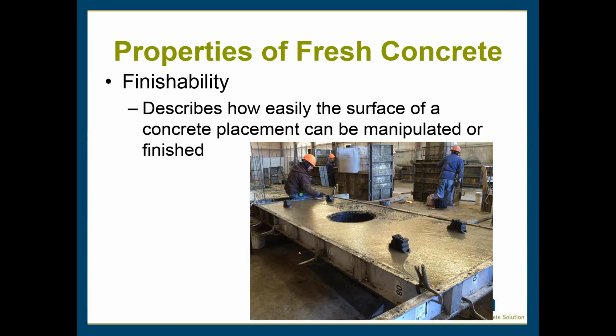It makes it a lot weaker, and sometimes if you rub your finger across it, it'll leave this dirty, cementy stuff on your finger. So it's not a good idea. Water added before the concrete sets will alter the structure.